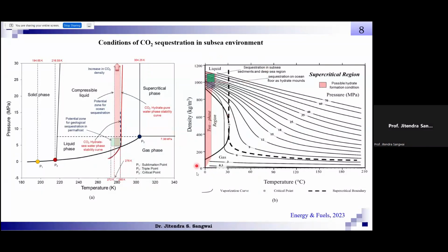You look at the density of the CO2 with respect to temperature. And these are the pressure profiles, this 3 megapascal, 6 megapascal, 9 megapascal, 12, 25, 35, right? And you have the temperature on this line. Let us assume that you are injecting carbon dioxide at, say, 800-meter depth, and assuming that your temperature is about 4 degrees centigrade, somewhere here, right?